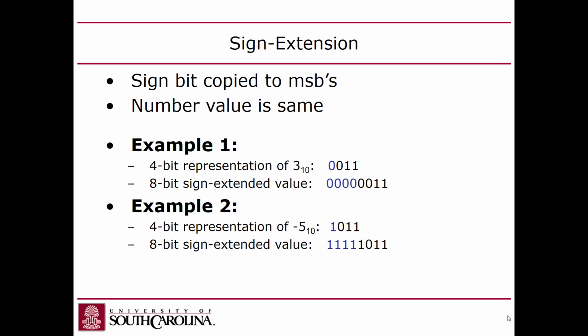So the difference is sign extension: take the sign bit, the first bit, and use that to add more bits, right? To change the width. If it's a 0 extension, then you just always use 0, regardless of the sign bit. Everyone with me? Okay.